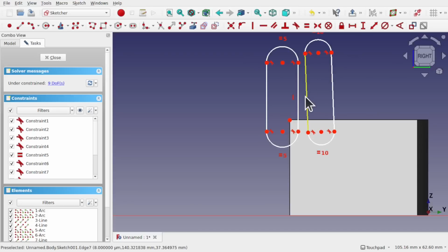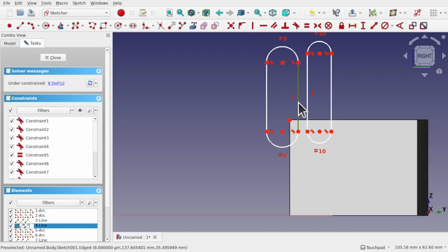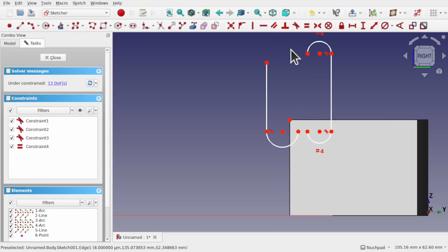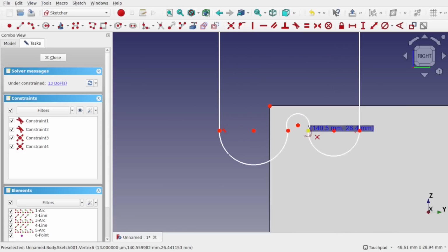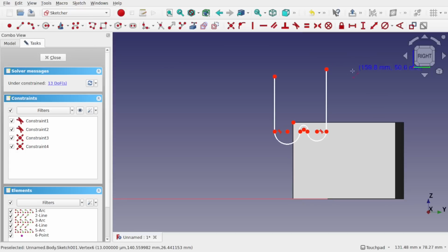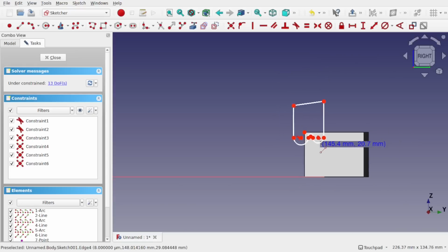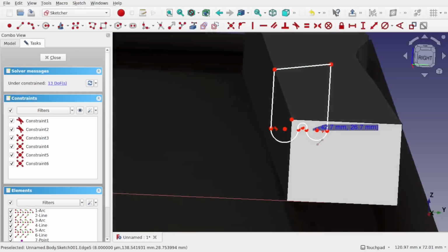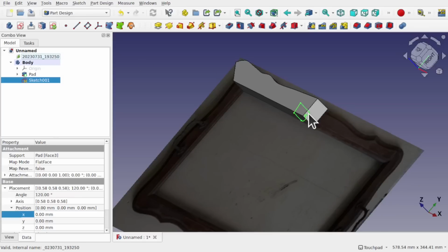Look from this side and we'll place some vertical constraints, and maybe let's take away this one and this one, delete those, let's take away the tops as well. I tried to take a shortcut with the arcs, so let's place an endpoint and rim point arc in here, something like that. So something like this, and very rough geometry, but what's going to happen if we do a pipe with this, it will remove this shape from this edge. So I've got the profile.